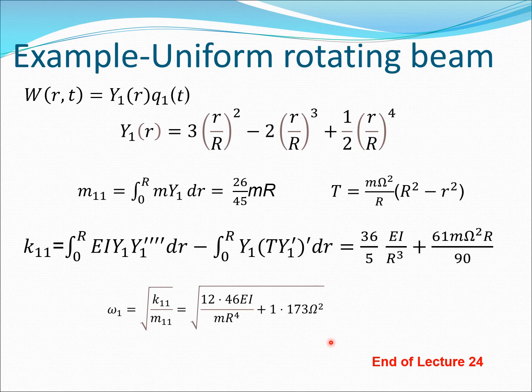So this is how you can obtain good closed form solutions, which you can use to calculate the rotating frequencies using the Galerkin method. Now, if you use more terms here, then your solutions will get better.